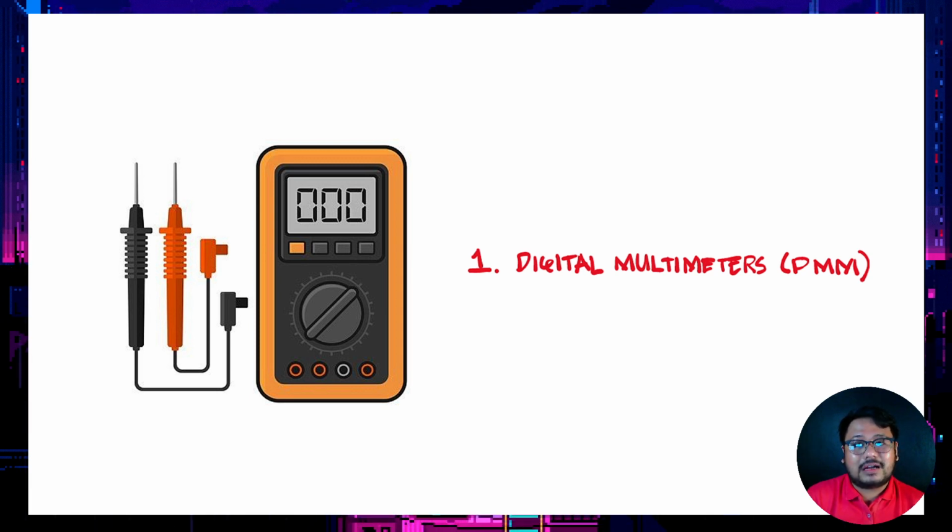The meter leads are color-coded. The black lead is connected to the common ground of the circuit and of the meter. The red one is connected to the slot depending on what is to be measured. Sometimes, some people refer to the red lead as the positive and the black lead as the negative terminal.